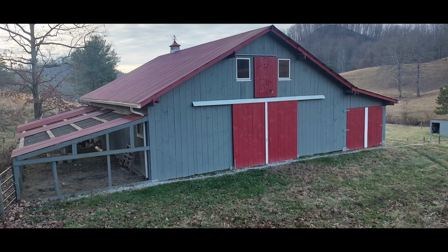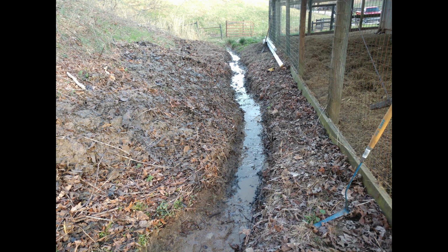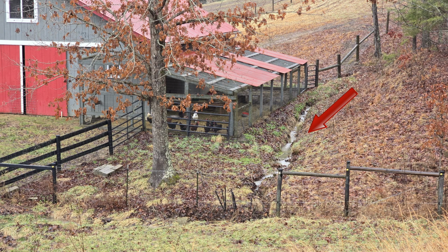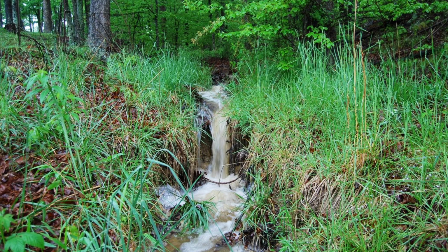The head cut began after we used a dozer to level an area where we built our barn. The dozer operator dug a shallow ditch along the base of the hill to divert water flowing in the ephemeral stream so our barn would not flood during a heavy rain. The ditch is called a diversion ditch because it diverts water around a structure or field. The ditch cut a slice out of the floodplain and channel of the ephemeral stream.